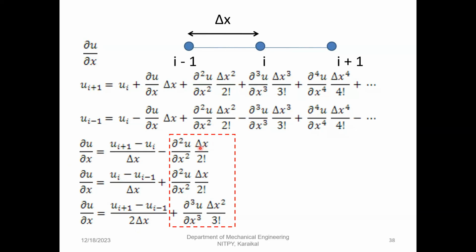So that means this error is going to have a magnitude of 0.1. This is going to have an error of magnitude of 0.1. This will have an error of 0.01. So that means there's going to be more advantage. The error is going to be lesser when I'm going to go for central difference. So this is what we'll be again choosing in Fluent. We can go for different methods. We can go with which method to choose.